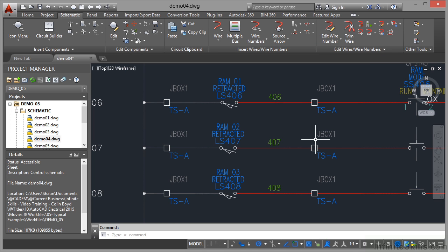You must use the editing tools in AutoCAD Electrical though. This is all linked to the AutoCAD Electrical database and you must use the tools provided. Don't just go in and use the AutoCAD text editing tools to change a wire number or a junction box number. And don't explode the blocks either because they are all linked, automated with parametric tools and block attributes and so on. The whole idea of this is to make your life easier. You will make your life much more difficult if you explode things in a typical AutoCAD electrical drawing.